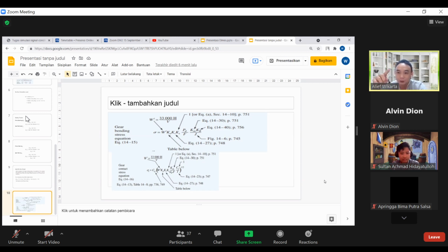For the average shear stress, the stress equals load divided by only the area. But when we consider bending, the stress equals load times the distance from the neutral axis to the point of interest, divided by the moment of inertia.